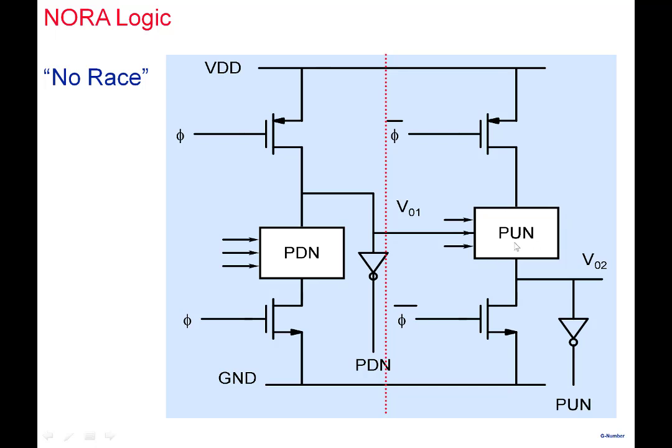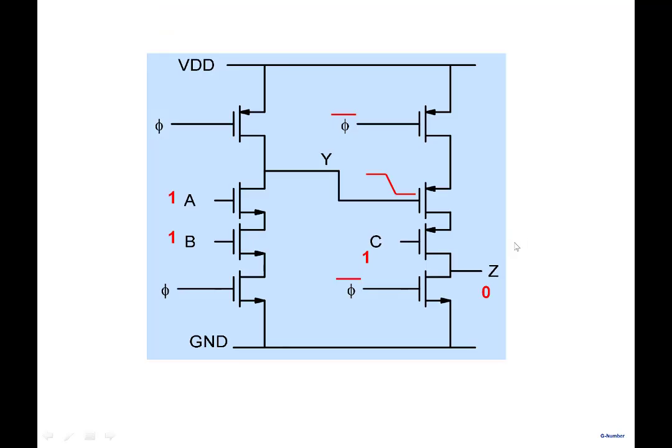When the Y goes from 1 to 0, then also for some part, when it reaches near 0, that PMOS will turn active. But 0 is the right output, right? 0 is the right output, so it doesn't matter. Note that the problem is that when you pre-charge, you have an incorrect output.